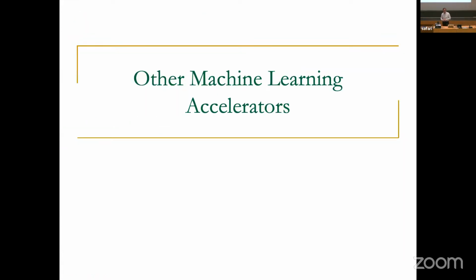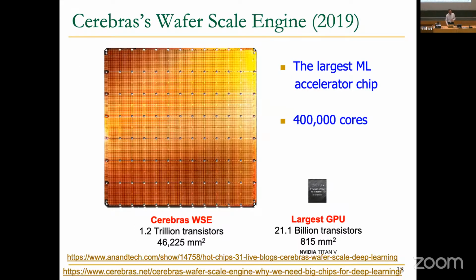So now, this is systolic arrays. As I mentioned yesterday, systolic arrays are not the only machine learning accelerators. Now we're going to see the SIMD paradigm that people have been using to accelerate machine learning, because SIMD is actually a very good fit for doing convolution-type parallel operations, matrix multiplication. And yesterday we saw how you can convert convolution to matrix multiplication as well, right? Remember that slide where I showed you that? You can go back to that. So basically, people have been using SIMD architectures, and this is later today. I will show you that at the core of it, this has many processors inside. Well, this is the newer version, if you will.